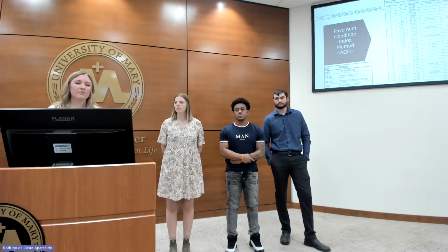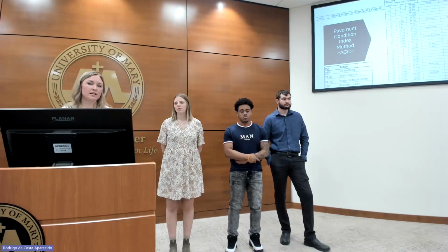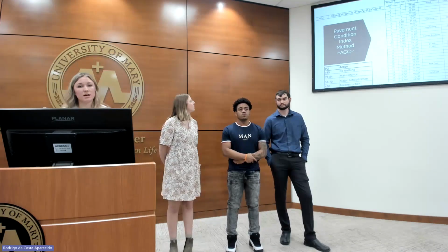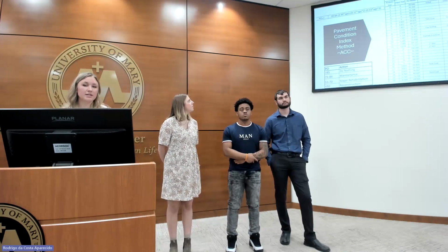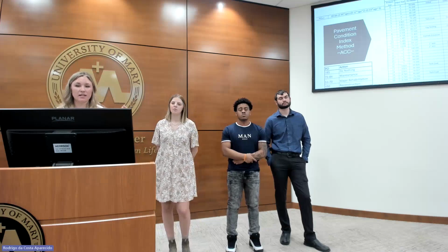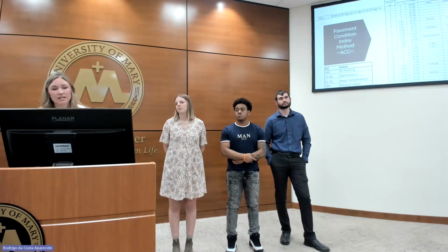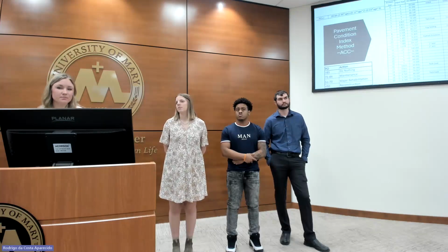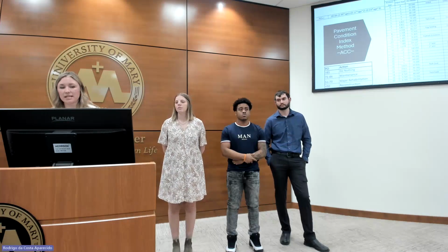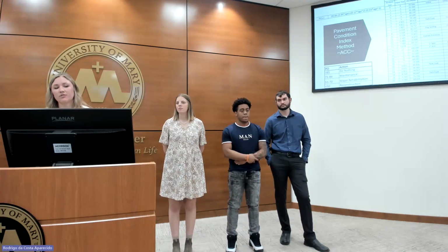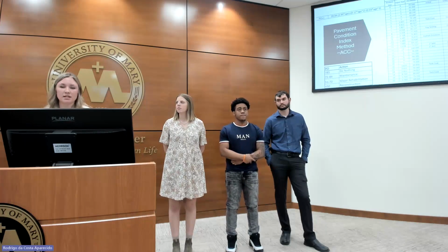I then used the pavement condition index method. I used the equation on the top, with the analysis period of 20 years, to calculate, given the year, how the performance of the pavement would be. If the rating was between 71 and 84, then I would account for maintenance to be done, and if it was 51 through 70, then for a major rehabilitation.